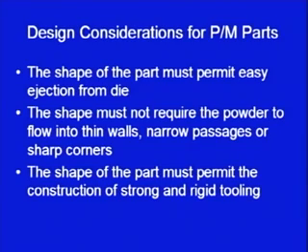So, the shape of the part is an important characteristic. We have to make a die in order to make a powder metallurgy part. So, the shape of the die is also limited. The shape of the die should be such that the part gets easily ejected. If the part is not easily ejected, then there are chances of breakage of the part.